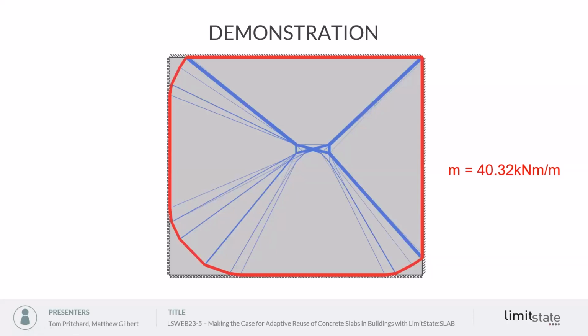higher degree of accuracy? Well, if you imagine that an existing building has slabs that have been designed elastically, like Matthew was saying, or perhaps using the strip method, and we know what the properties of that slab are, then we can use this automation of the yield line method, the flexibility of the software and the precision that it provides to work out whether that slab then will have sufficient reserves of capacity that it can withstand any proposed modifications to the usage.